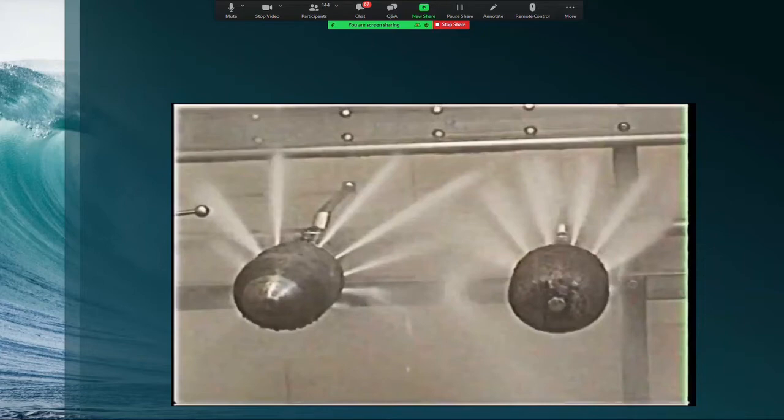We did have one question come in. Some of the audience members are looking at using these kinds of jets to clean struvite, magnesium ammonium phosphate, out of pipes. I know you're kind of doing an overall education now, but to address that specific question, I won't get into detail on that, but yes, and you'll see some videos in a bit of different styles of nozzles that are intended for exactly that job. Struvite is quite hard and is difficult to remove. There are tools to get at it. If you're working in a treatment plant, you know what struvite's all about and you have had to deal with it. A little later in the presentation I will make sure I bring that up at the time and point it out.